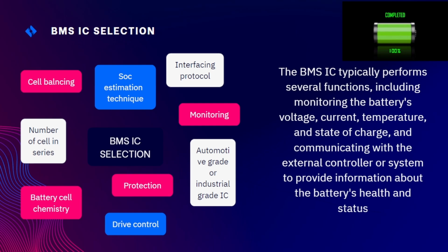Over voltage condition can destroy the battery's life, that means the state of health of the battery, and in some events can cause a fire if high enough. Under voltage conditions lead to an inefficient system where charging may not be adequate and the system may not output sufficient power.